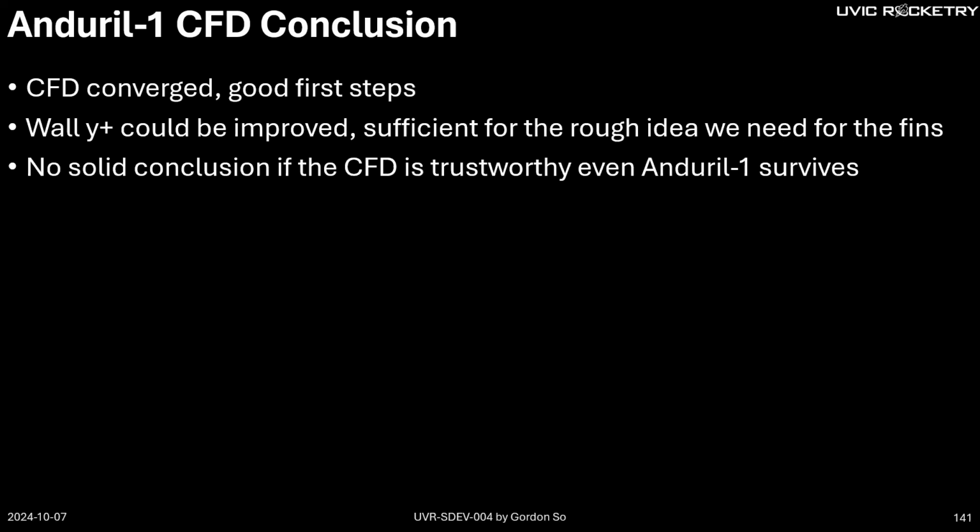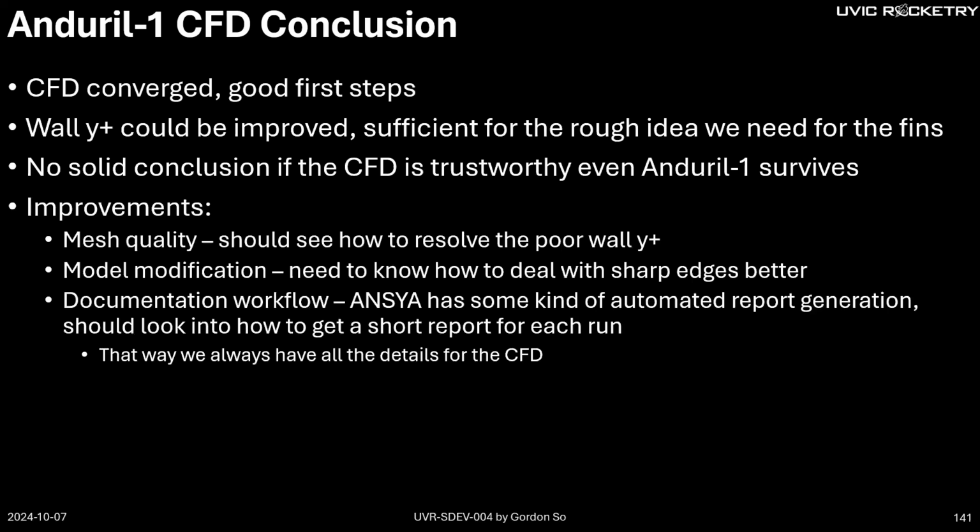Although that is the case, that's just after the fact, so I won't say the CFD is, to be honest, trustworthy. It's just a good starting point. There's some improvement that I think we can do to make it better. The first one is mesh quality. We really need to see how to make a better mesh for near wall, like Y plus, how to achieve proper Y plus.